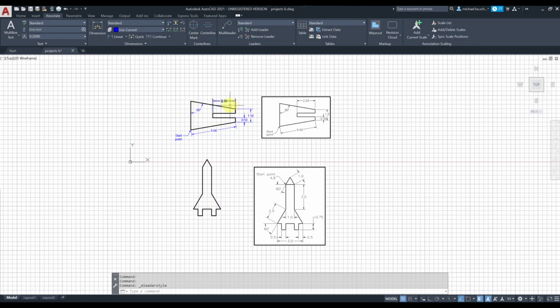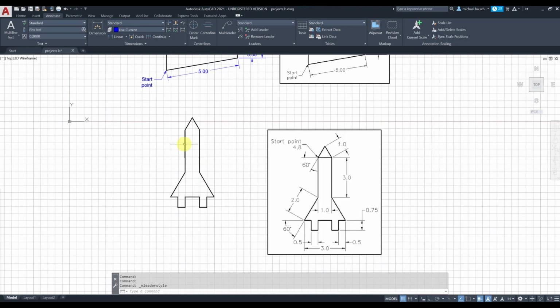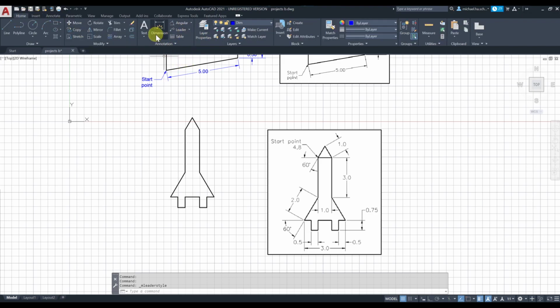We're gonna practice the same thing on the second project. Okay, and we're gonna move a little faster this time. So I'm gonna go to the home tab and try to use this. This is pretty smart, and you don't have to keep choosing different type of dimensioning there. The way I suggest is add the smaller dimensions first, and then much larger further away dimensions. So let's go ahead and, for instance, add